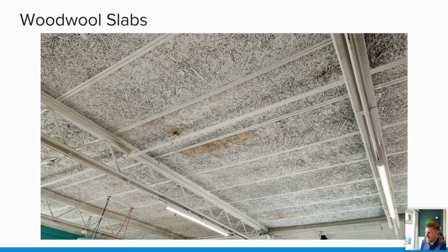Paper faced, pre-screeded woodwool slabs. So sometimes you'll come across a concrete screed and then you'll dig down a little bit further and you'll find that it's woodwool. That's a pre-screeded woodwool slab. The NFRC have put quite a good guidance note together on woodwool slabs and whether to replace them or whether to overlay them. So I'd recommend having a look at that.